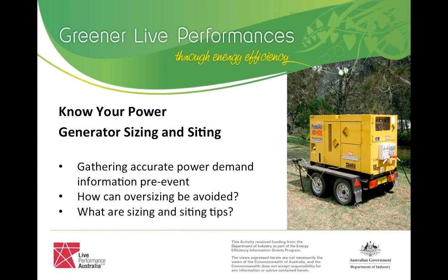Yeah, so I think you've hit on something there that I have seen come through, and I've been discussing with a lot of event organisers, that obviously if there's mains power available, this is what you want to be taking first up, and putting your 24-hour loads onto that is probably the best thing, because then you can actually shut your generators down. So I think that's definitely a trick.